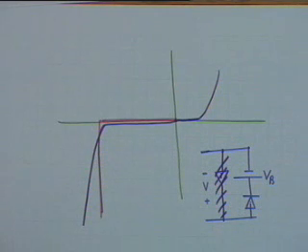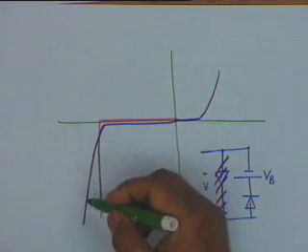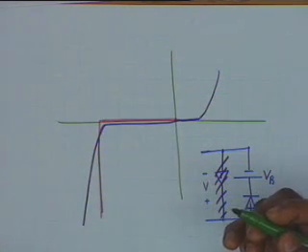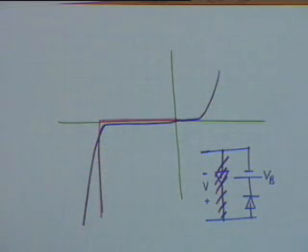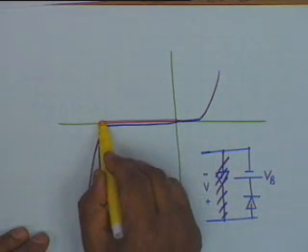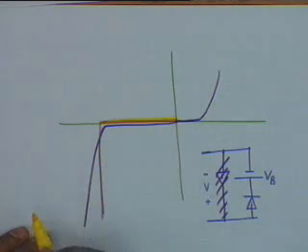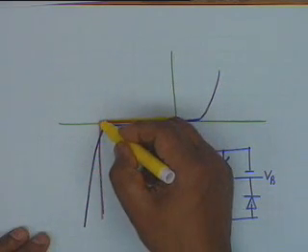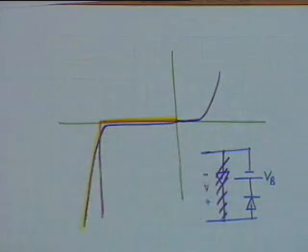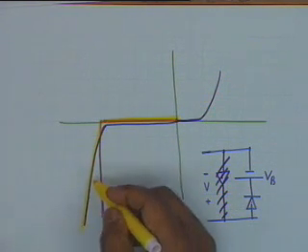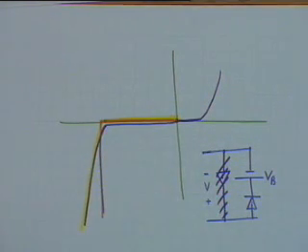Now, once again, the sloping character of the actual Zener diode can be approximated by including a resistance. I should use some other color, let us use yellow. We approximate up to this, the yellow line, and then we approximate by a straight line whose angle with this axis is slightly less than 90, and you can define a dynamic resistance for this characteristic.